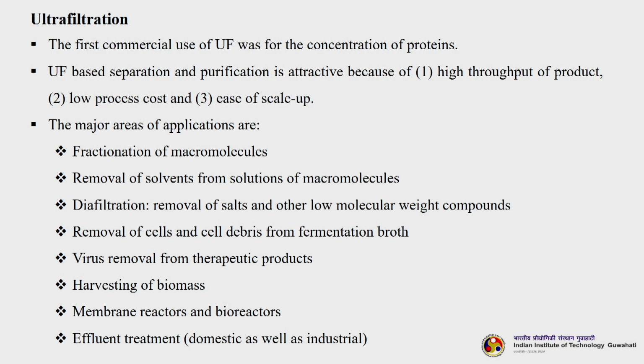They are fractionation of macromolecules, removal of solvent from solutions of macromolecules, and diafiltration. Diafiltration is a classic example or a mode of operation of ultrafiltration. I will show you the scheme later on. Here, the removal of salts and other low molecular weight compounds is carried out. Then there is the removal of cells and cell debris from the fermentation broth, virus removal from therapeutic products, harvesting of biomass, that is, mature cells, membrane reactors and bioreactors, and effluent treatment, both domestic as well as industrial.